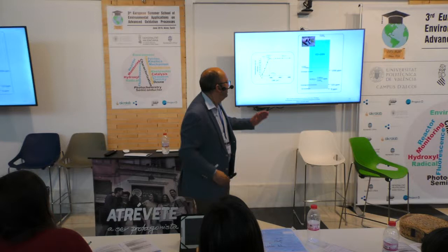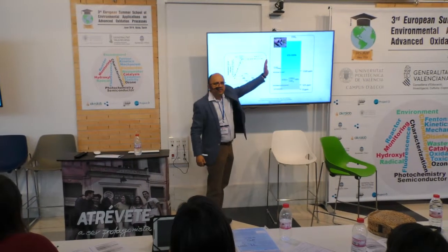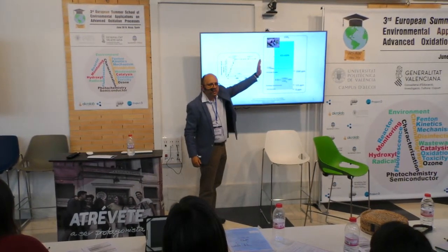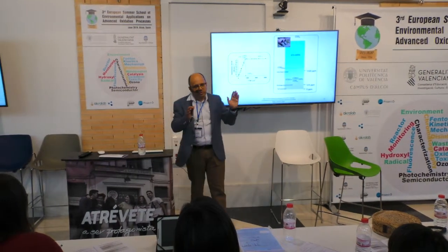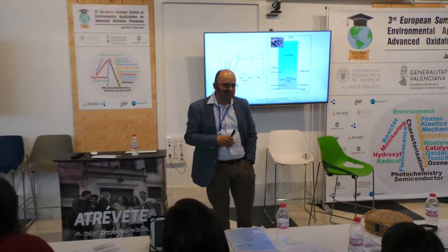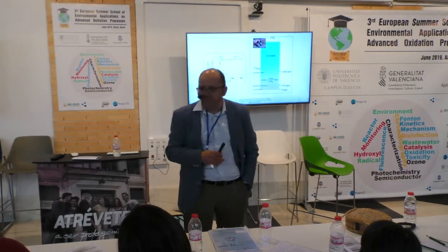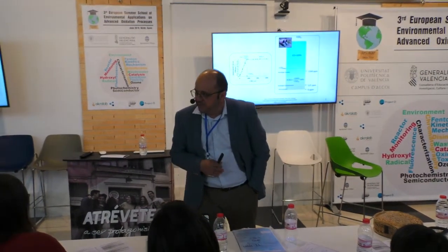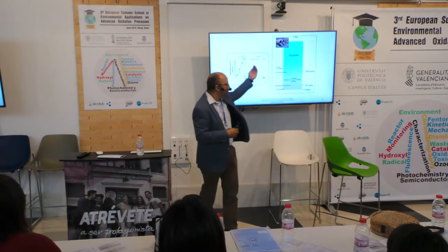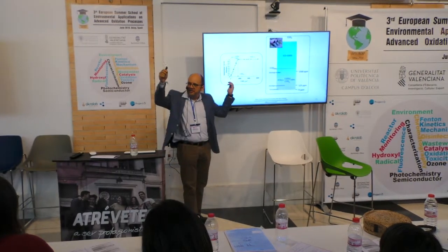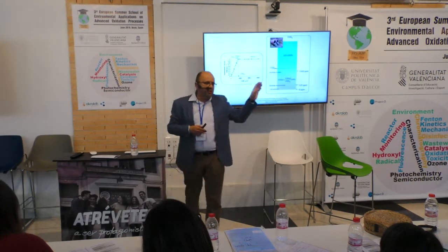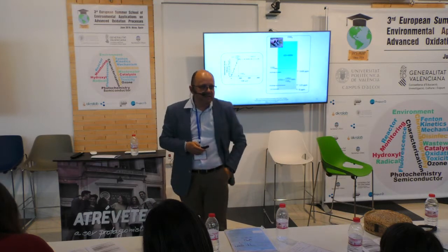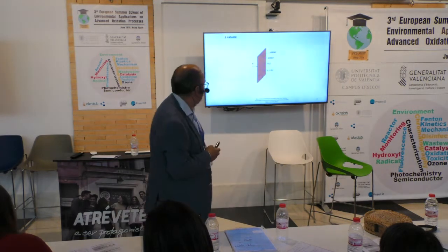You can have 100% efficiency by working from a very high value down to more or less 1,500 ppm of COD. And from this value down, you have a linear decrease in the efficiency of the process. This is a typical value for a typical commercial electrochemical cell.